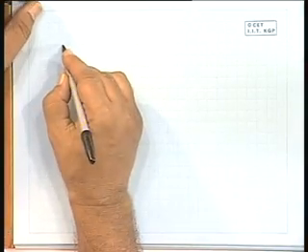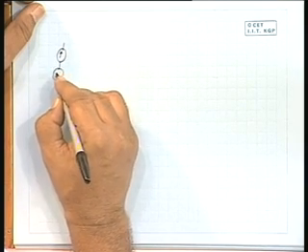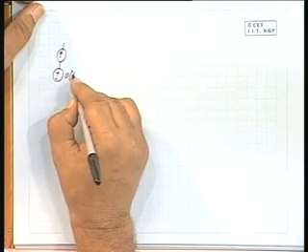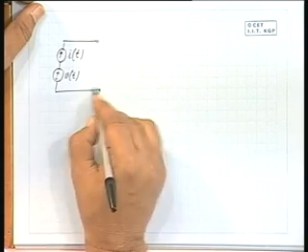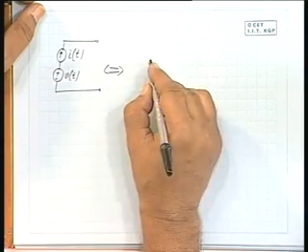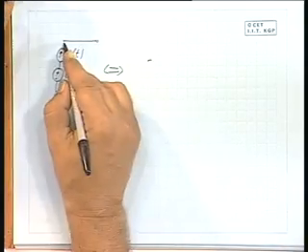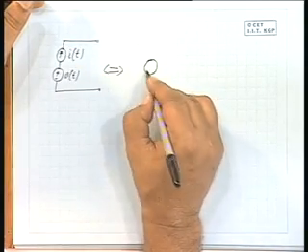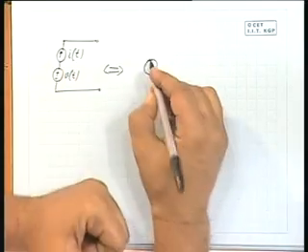Similarly, if you are having a current source in series with a voltage source, what will be the equivalent? It will be a current source, because the same current has to flow through this. So, voltage source becomes redundant, all right. There is no influence of the voltage source here as such.